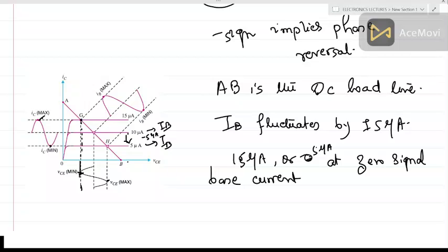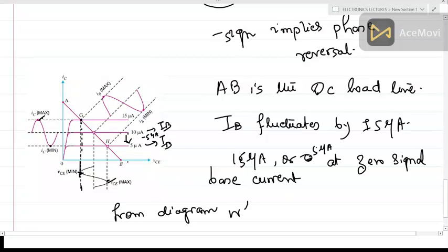This is the input signal. So, when I see the input signal is minimum, it is reaching the maximum in the negative direction, the output is reaching the maximum in the positive direction. This is the meaning of the phase reversal, phase opposition. So the input and output voltages, let me write this thing in detail.